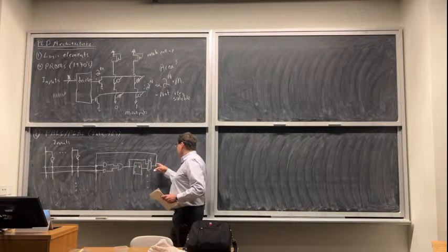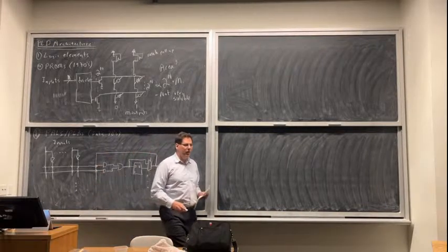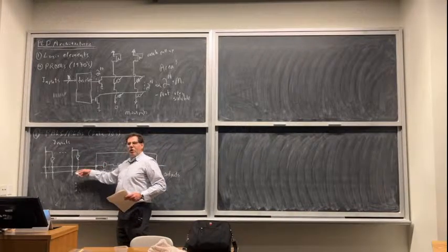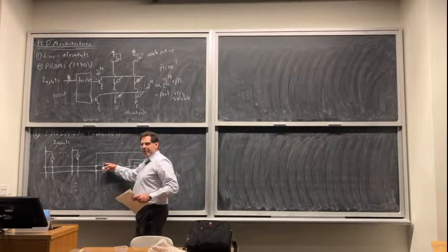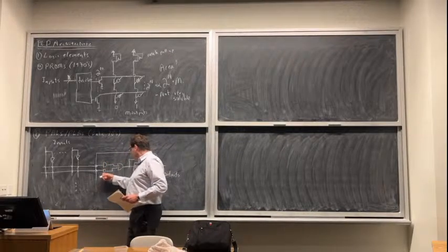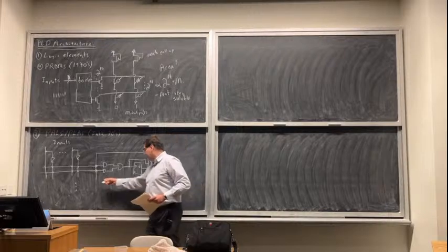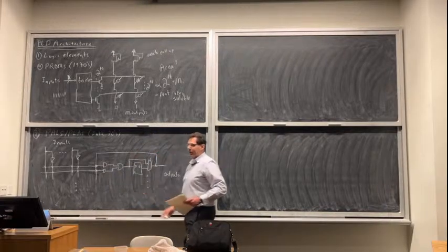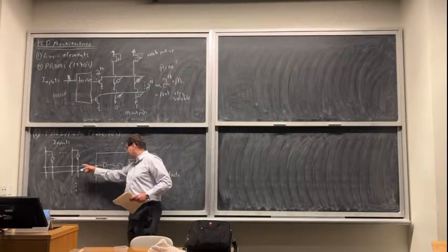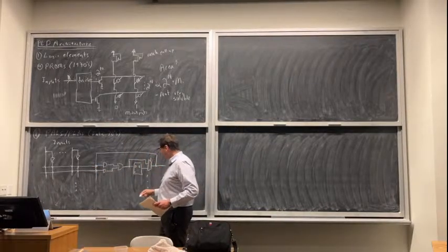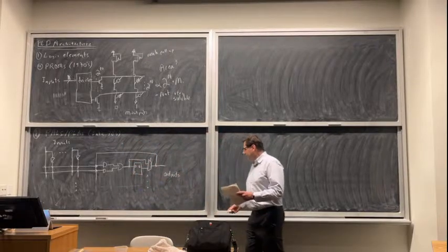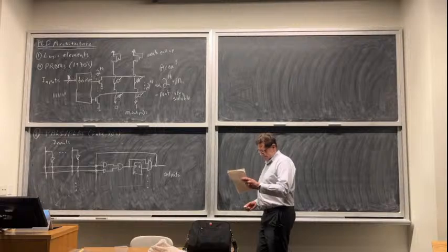And you have this ability to feed signals back so that you can do sequential logic, or maybe you just found your logic was complicated enough that you needed to do a 5-input AND and then feed it back, and then in another one of these, what is called a macro cell, you might do some more ANDing. So feeding this back is useful for sequential logic. It's also useful if you've just got really complicated combinational functions. You can pass through one of these, and there's another one down here. You could pass through another one to do some more ANDing and some more ORing. So does that make sense?